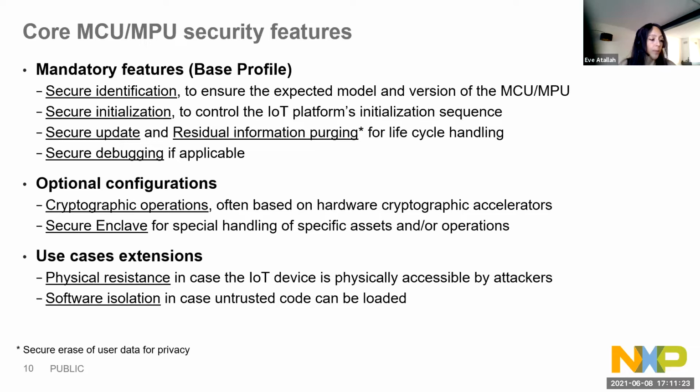Optional also, some of the assets and operations may need to be handled in a separated execution environment that we call secure enclave, as for instance, the storage of the private keys and/or the execution of cryptographic operations. So the secure enclave needs to be an enclave, of course, meaning with its own separated execution means, but inside the MCU and secured in some way by software or hardware means. So it can provide a higher level of security or not, but it must at minimum be providing either a logical isolation or hardware protections.